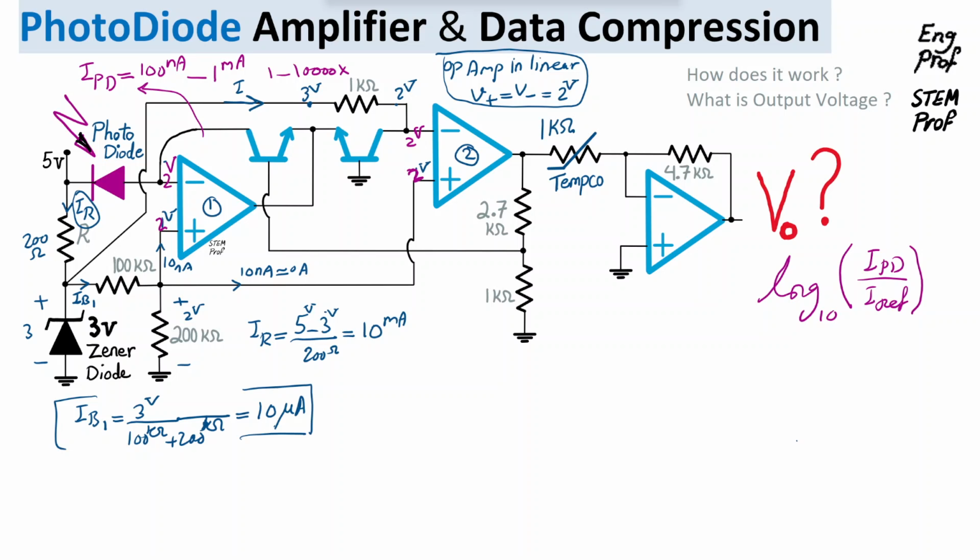Let's say I name these transistors as transistor T1 and transistor T2, the matched pair of NPN BJT transistors. Effectively this current is the collector current of transistor T2, because it will go through the 1K and then can only go through the collector-emitter of transistor T2, through the common emitter, and then through the output of op amp number 1.